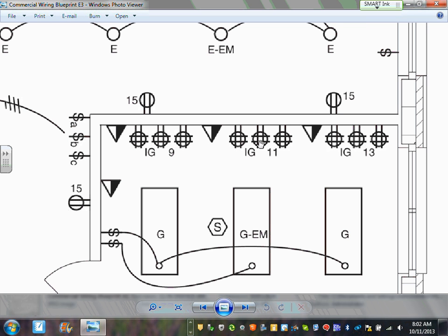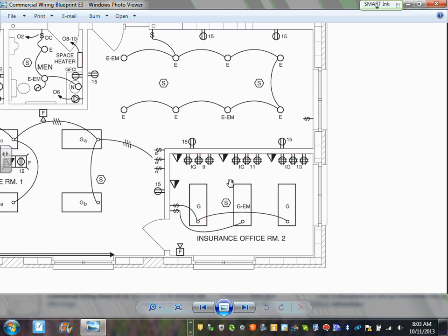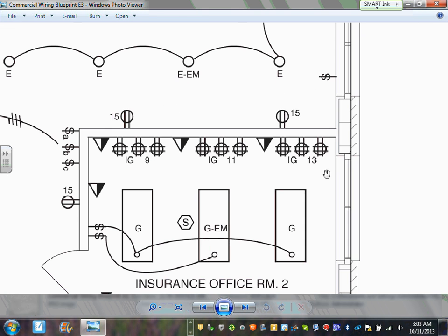This quad is a 4 receptacle, 2 duplex. Can you guys see how they put a lot of quad receptacles there? When it says IG, that is insulated ground, because they're crunching numbers for your insurance so they can charge you and charge me, they're having an insulated ground, guys, so they don't corrupt the data. We'll talk about insulated ground receptacles, commonly used when you're crunching numbers and when you don't want to interfere with the operation of your data. Insurance is a good example, banks, any place where they crunch numbers and store data.